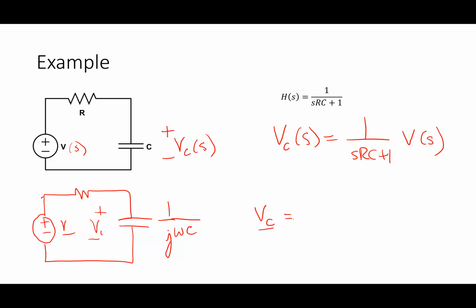How would I approach that here? If I want to solve for V sub C in terms of V, how would I do that? So it's just V minus VR. It is, but it's a voltage divider, isn't it? Yes. Okay, so help me out. How would I do the voltage divider here? It'd be V phasor over R plus ZC, all times 1 over J omega C.